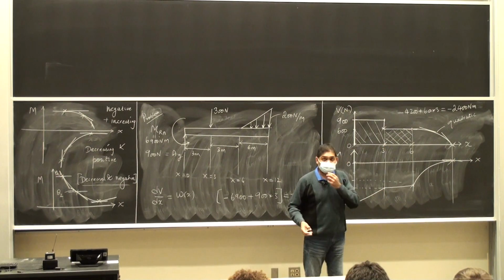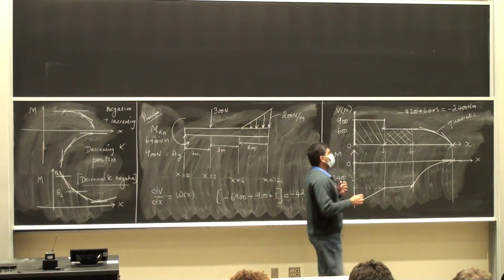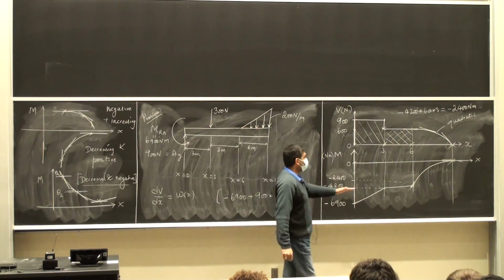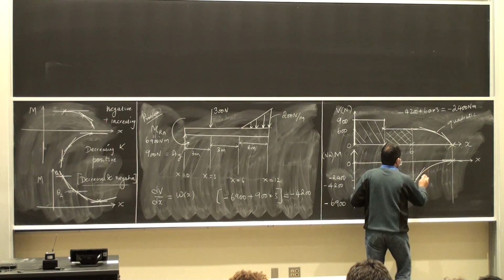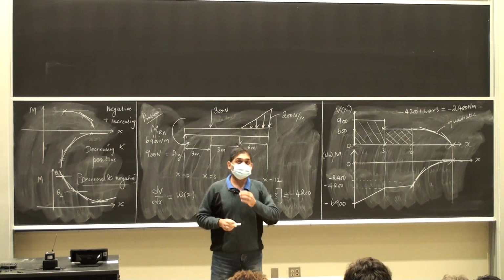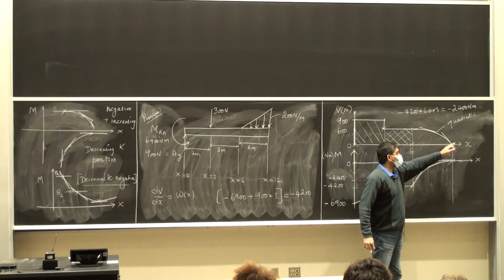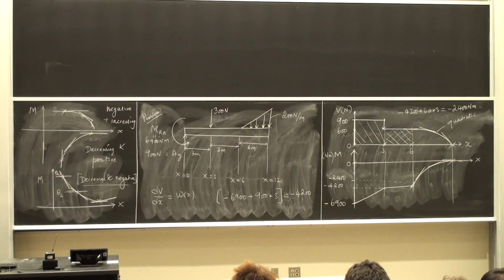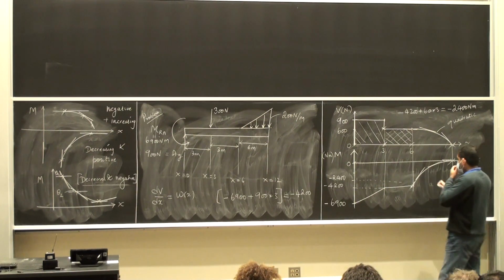I start off at a large value of the slope, so probably the same as, there should be some continuity there, so I apologize for that. Should be the same as the slope here, okay? My slope is decreasing. Why is my slope decreasing? This is because the value of the shear force is dropping from 600 to 0. What's the nature of my curve? It's going to be a cubic because my shear force diagram is a quadratic. So this is a cubic.